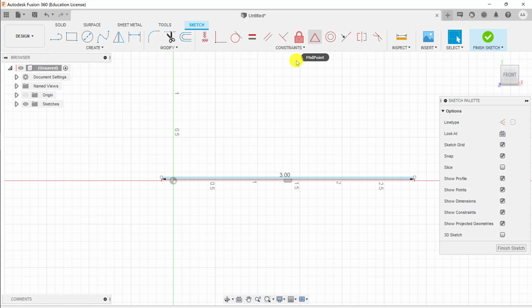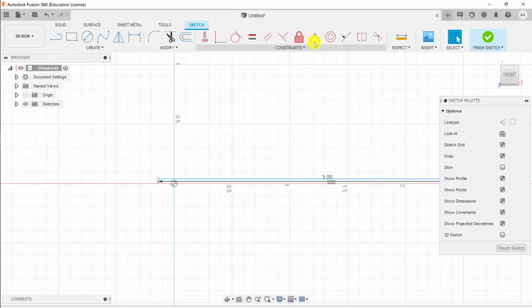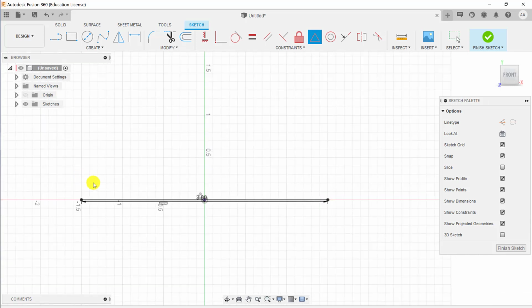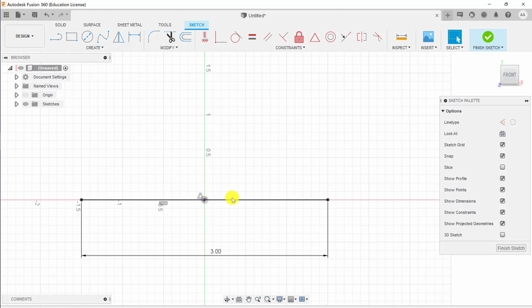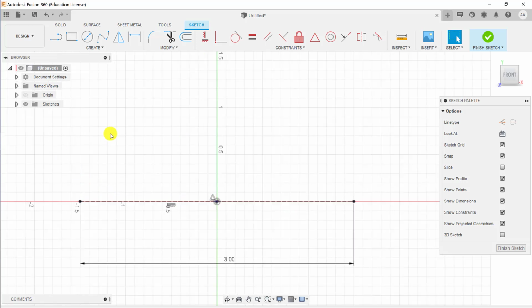So now that we have the wheelbase line defined, we can constrain it to our sketch. So we're going to constrain the midpoint of that line to the origin and make it a construction geometry, because this is not part of our actual vehicle. So the way we make it a construction geometry is we click on the line and then hit the X key, and you can see that it's become dashed, and that means that it's construction geometry and it's just used for reference.